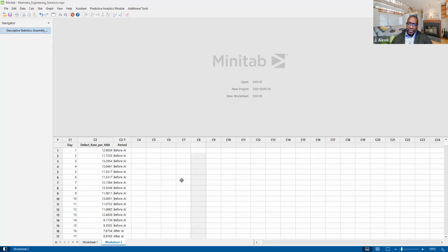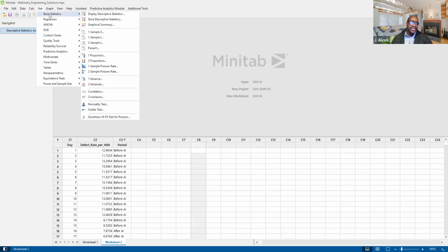So for this test, because we have two samples, we're going to perform what we call a two-sample t-test. If you can do this with me, click on Start, Basic Statistics, and two-sample t.